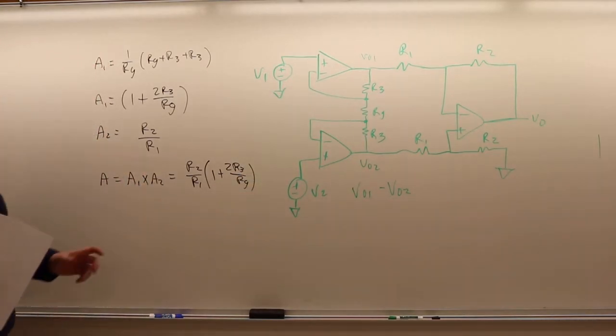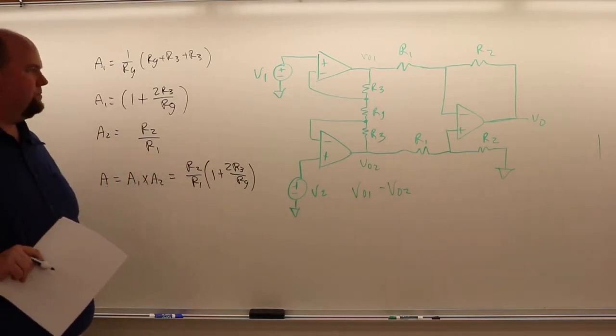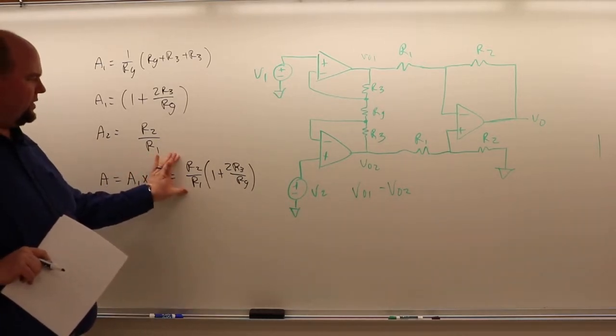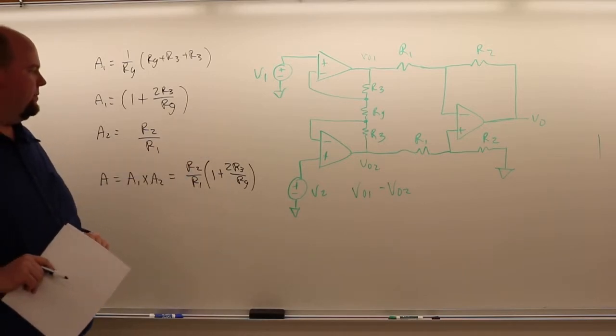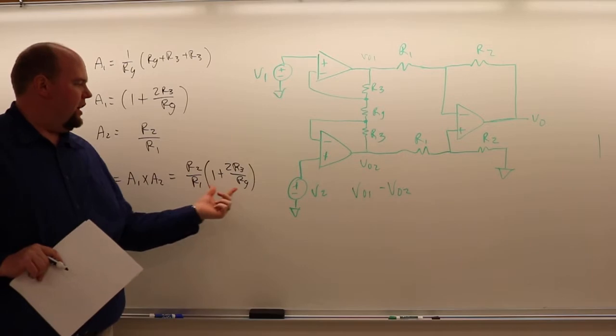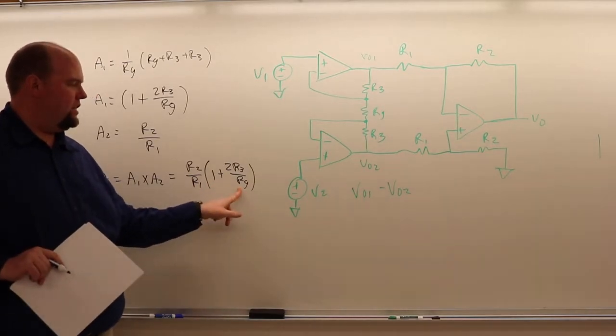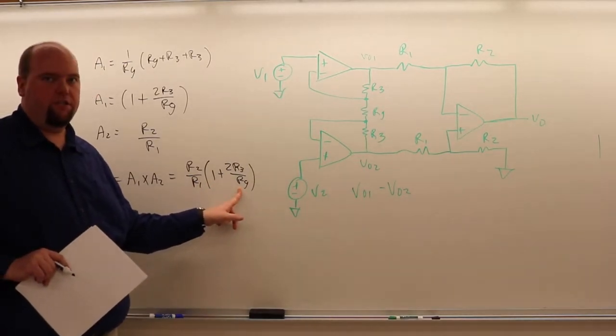So again, in practical amplifier designs, we're going to have some gain here with this R2 over R1. That's typically going to be built in internally to the amplifier. And then we're going to have some programmable gain here that can be determined by setting this value of Rg.